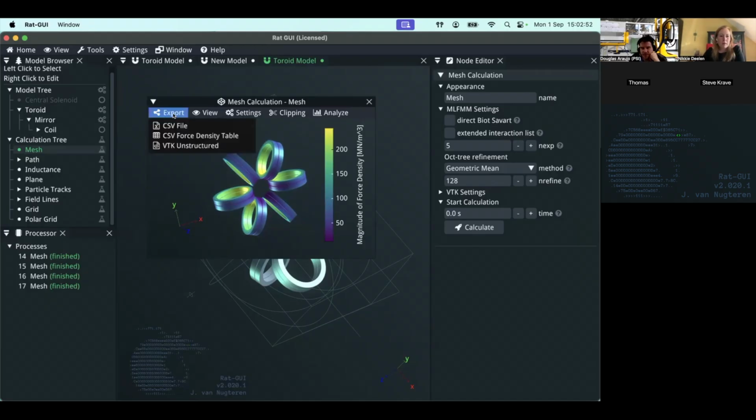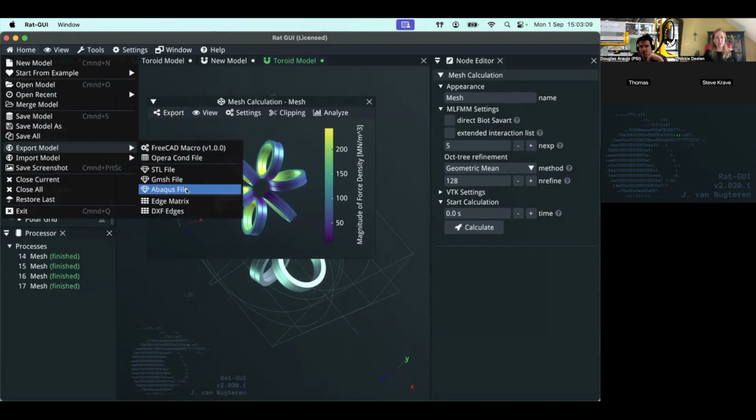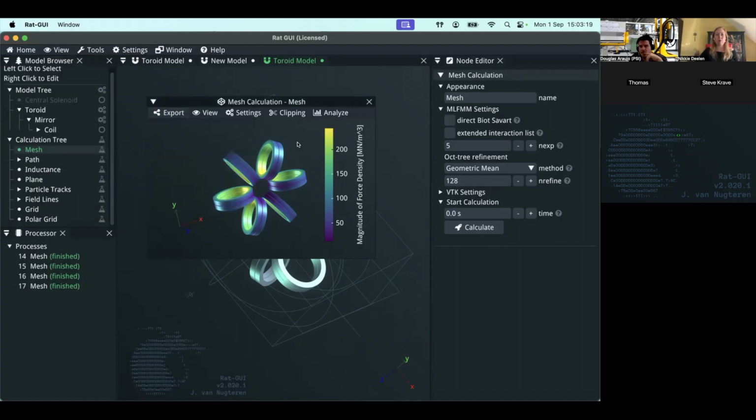Maybe you are referring to the nodes, because to do a 3D mechanical model, we would need the coil shape, to, let's say, subtract it from a former or something like that. Maybe it's the edge. Exactly. It's probably one of these. So what you could do if you use ANSYS, I think we always recommend people to export it to FreeCAD. Then you can make a STEP file, and the STEP file you can import in ANSYS, and together with this force density map, ANSYS will figure it out, I think.